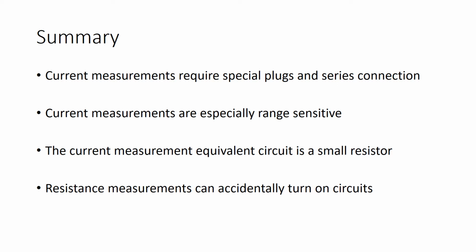The equivalent circuit for resistance mode is a big resistor, just like the voltage mode measurements. The only difference is that in order to measure a resistance, your multimeter needs to actually supply power to the external circuit. This measurement works by shooting a little bit of current out through your terminals into the world and observing how much voltage develops across the multimeter as a result. Because it knows how much current it's sent, it can relate the voltage it observes to the resistance out in the world. Because you want all your current to go into your circuit under test and not your multimeter, you use really big input resistance on your multimeter again, so that's the 10 mega ohm resistor that's pictured in this figure, just like for a voltage measurement. And that should reduce the loading effects of your measurement circuit on most small resistors.